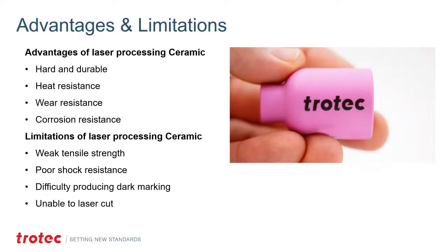This is primarily marking, is all we're going to cover in this segment. But as you can see in the sample I'm holding here, this is just a welding tip of the Alumina Ceramic. The contrast is outstanding. We're able to get that black, almost kind of like a Surmark, in the fact that it takes the ceramic coating and actually fuses it, turning it to glass, and produces a black mark, which is a great effect with just a standard CO2 laser, which I'll illustrate here.